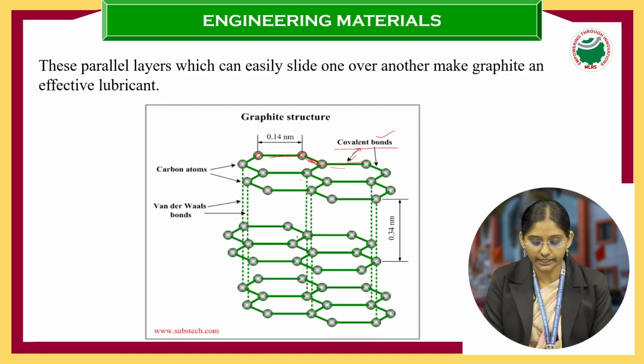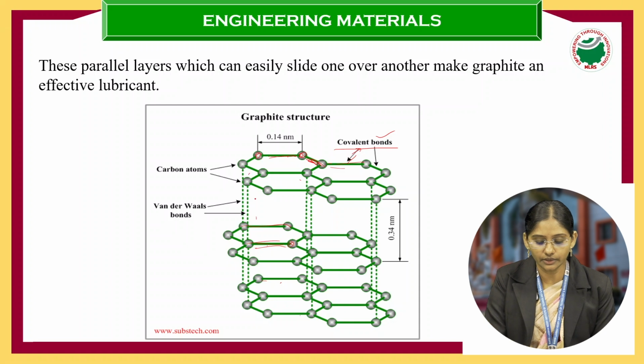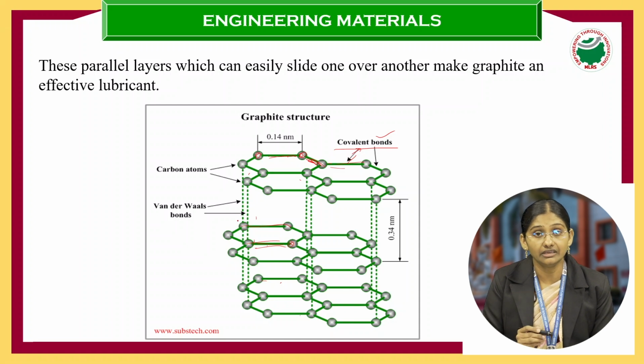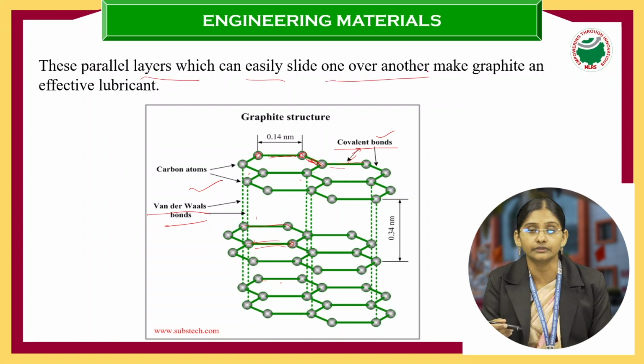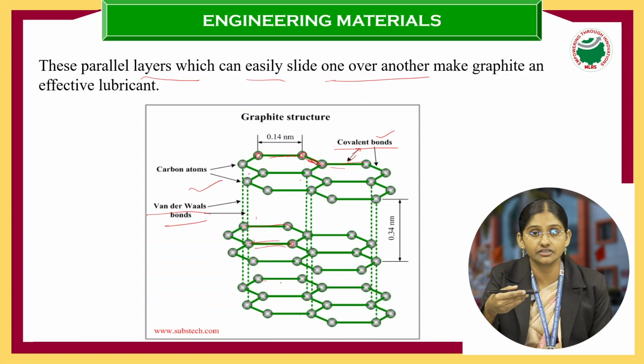And next, like this, one more layer; here also the covalent bond, and next the third layer, here also the covalent bond. Now if you see the two layers, these two layers are bonded together by weak van der Waals forces. So these parallel layers can easily slide one over the other because of this layered structure.